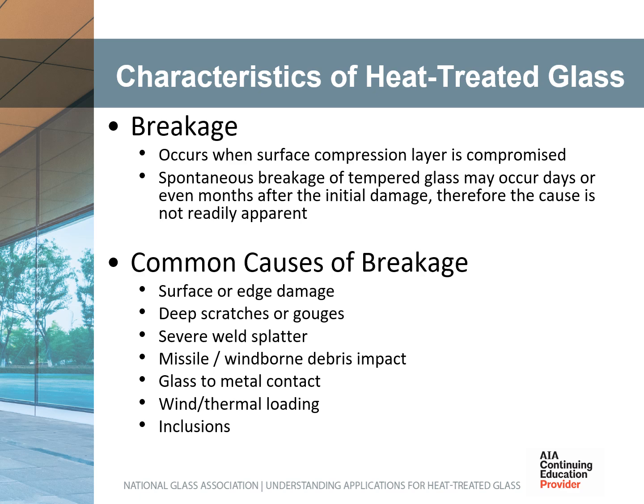While heat-treated glass is very strong because of the high compressive stress developed at its surface, it will break when that surface compression is breached, either from within or without. The majority of heat-treated glass spontaneous breakages are from one or a combination of the following causes. 1. Surface or edge damage. 2. Deep scratches or gouges. 3. Severe weld splatter. 4. Missile or wind-borne debris impact. 5. Glass-to-metal contact. 6. Wind and thermal loading.